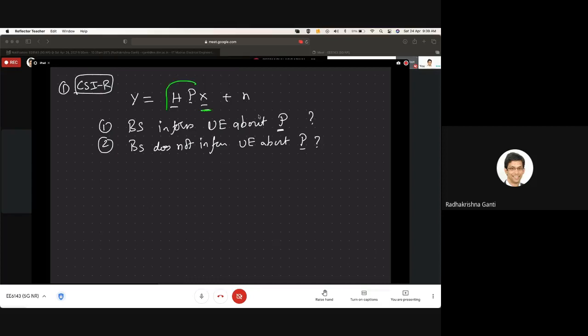So, according to the UE, the effective channel is H tilde, where H tilde is nothing but the channel times the precoder. It is not worried about what is H, what is P. But nevertheless, what you say is true. I'll come to that point later.